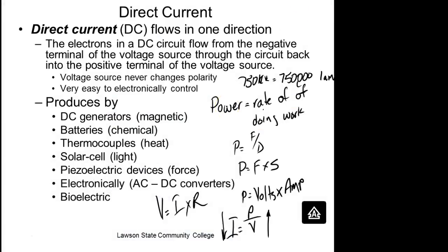So what we do, we have two types of current. This is what the guy down there said. He said we use transformers to step up the power. You don't use transformers to step up the power. You step up the voltage. If the transformer was 100% efficient, then power out equals power in. So transformers don't change power. They change the voltage.